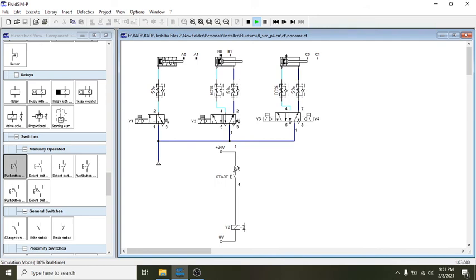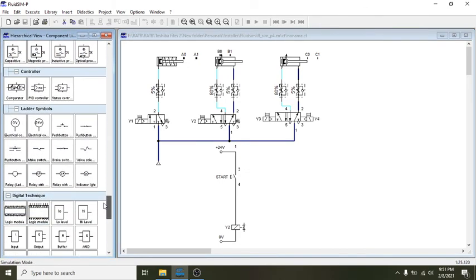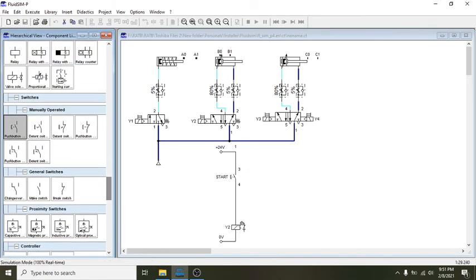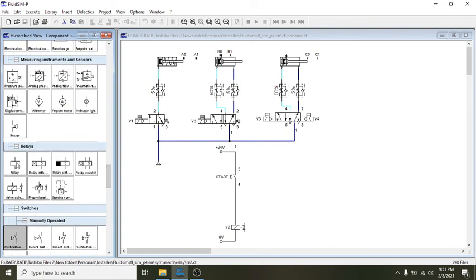So we need to make sure that the cylinder will be able to reach the farthest point it can extend, therefore we need to maintain the operation of the coil Y2 by having a sealing contact.